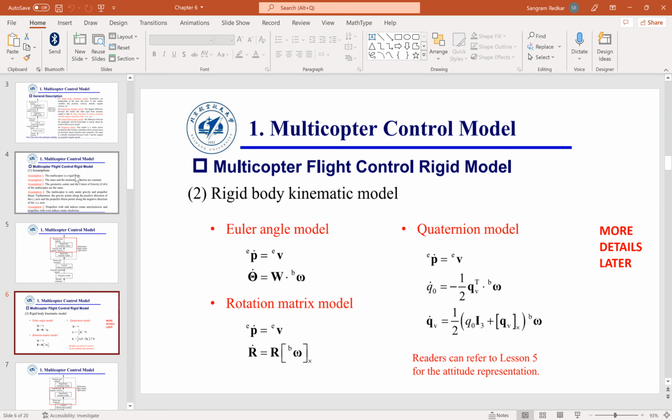Now imagine a case where the UAV is rotating 10 degrees per second in yaw and 10 degrees per second in pitch. Now if I ask you, tell me after 1 second what is the final orientation, you can't say with confidence it's 10 degrees in roll and 10 degrees in yaw. Why? Because in addition to those rates, the orientations have also changed. What it means is you will have to solve a differential equation to propagate those values. You can't just simply integrate. The differentiation that comes in the rotation matrices comes into the picture and will change those values. That is the inertial navigation problem, and we'll talk about it.